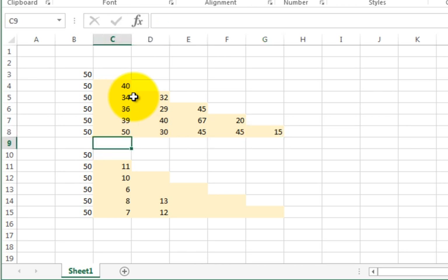So if I came in here, I said, this is my energy balance equation, I would have to put the K times A over L times blah, blah, blah. So over here, I'm going to use something that some students showed me in Excel. It's called naming. I'm going to name some things. Let's say I'm going to call it dx. That's my spacing distance. If you just put dx, it may think you're looking for a column dx, so put dx underscore, and then it's a variable name, all right?